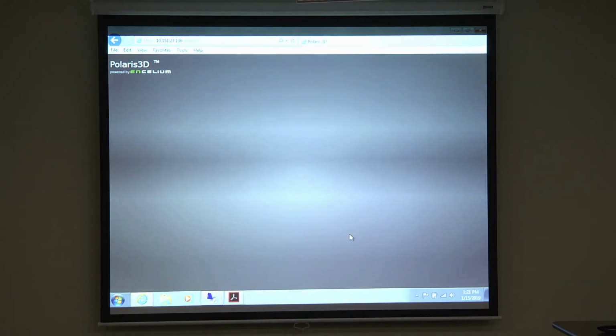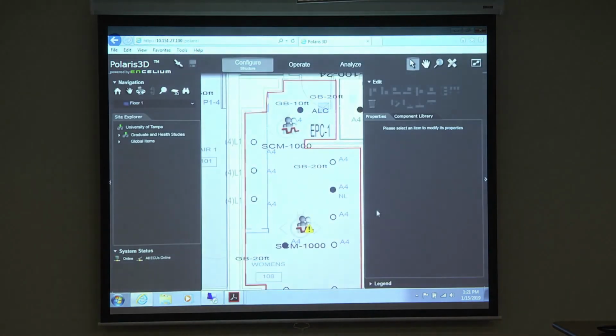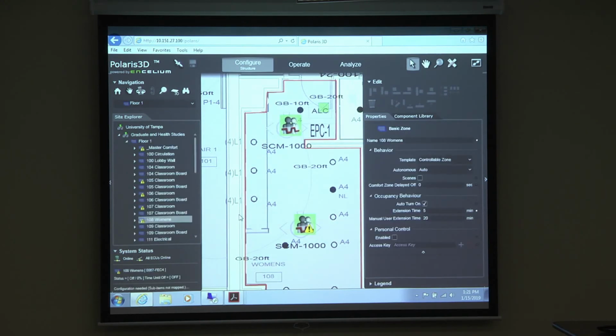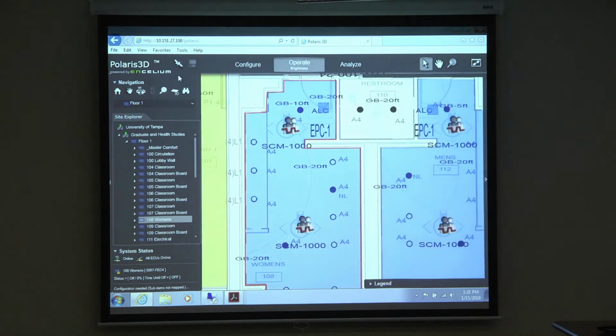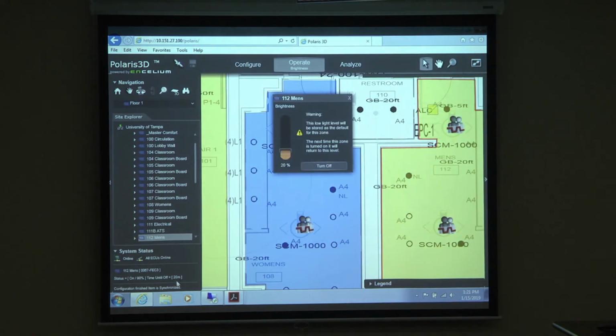So that zone I just did a while ago has a timeout of 15 minutes total. In the back of your head, just know that the hardware timeout is 10 minutes. Click on the zone, the 5 is already there. Before, when you did that, we had this as 20 and then a 1. The 20 is the manual extension time. Manual meaning if I manually turn it on. If I manually turn this one on here, see, 20 minutes, the manual right here.